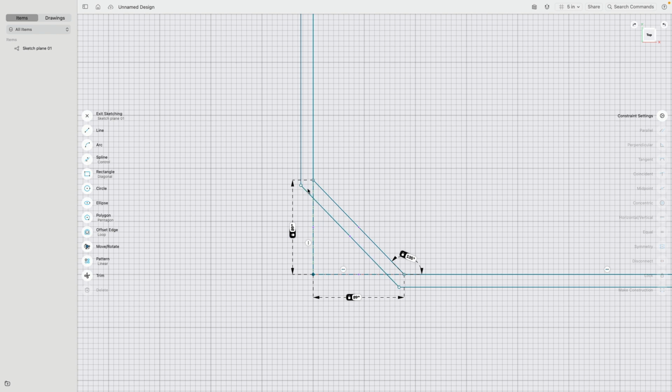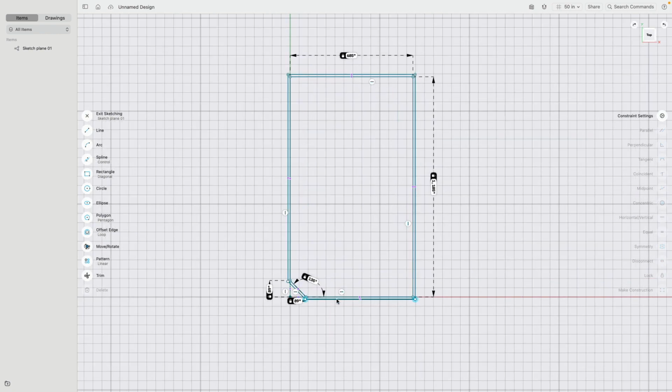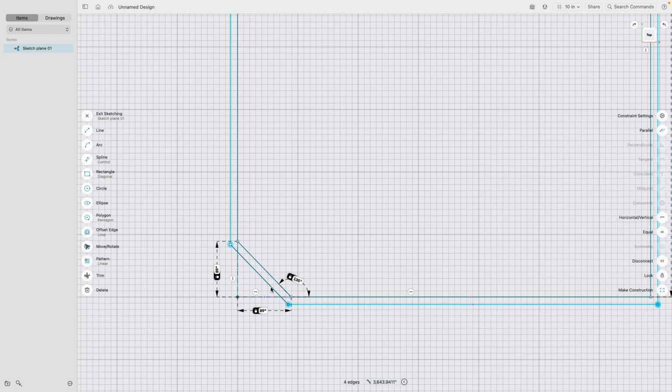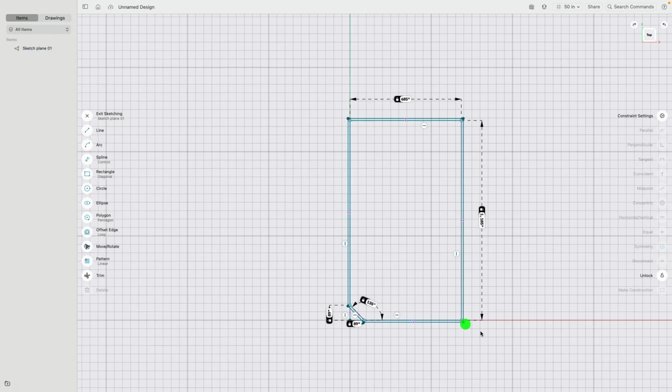And you see now here, these construction lines didn't really bother anything. So this is perfect. To make sure that these lines don't change at all, I will select them all, including this one, and then simply lock it. It's kind of like freezing in AutoCAD. Very good. So I can click, but nothing can work or change. There we are.